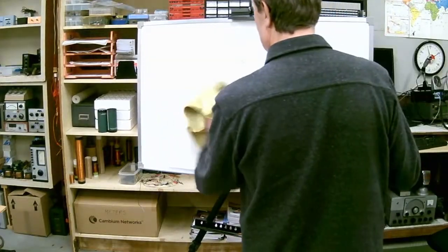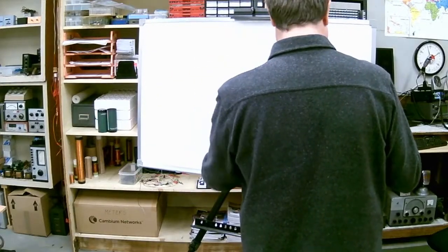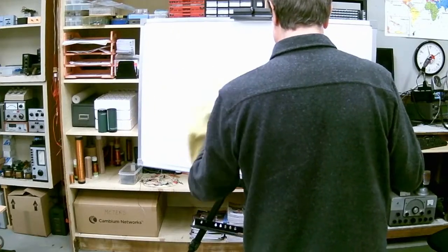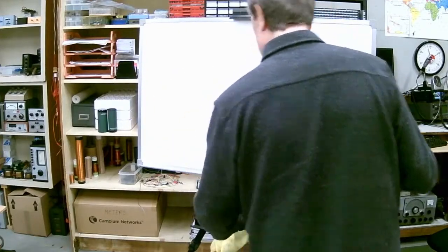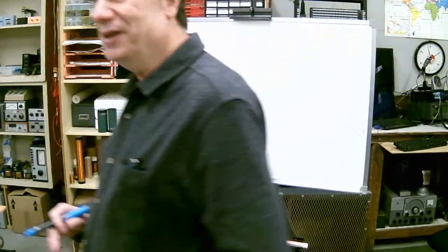Ground propagation. And that's for certain wavelengths, you said, like lower frequency? Yeah. Get up to high frequency like VHF, the loss to the Earth is so tremendous anyway, you don't normally use it. So yeah, you spend all your energy heating earthworms up.